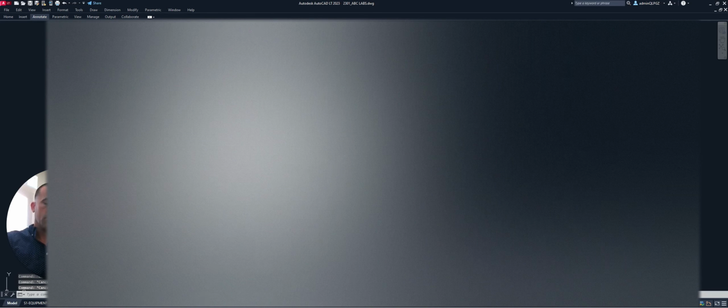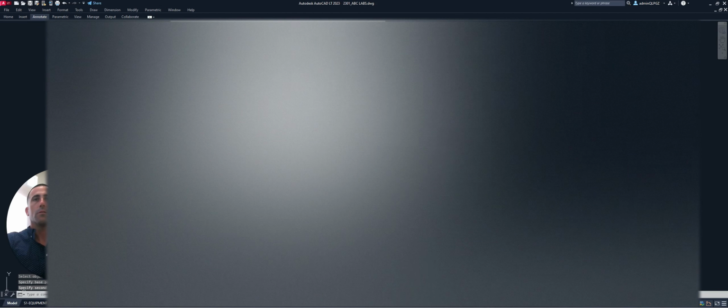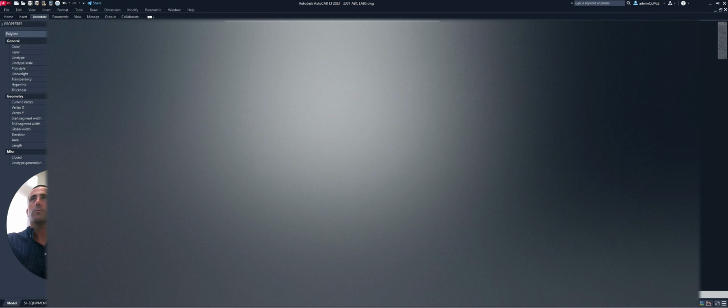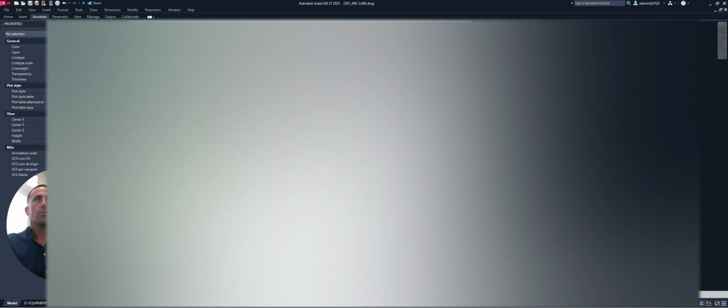That's good. I'm going to move all this other garbage out of the way, other things I've drawn, just standard stuff. Alright, click the properties on this. Right now I'm operating on the layer 02 paper space. I want my concrete to be on 20. Just my CAD standard that I like to use. Okay, so here is our slab. So 6 foot wide, 13 feet 9 inches long.